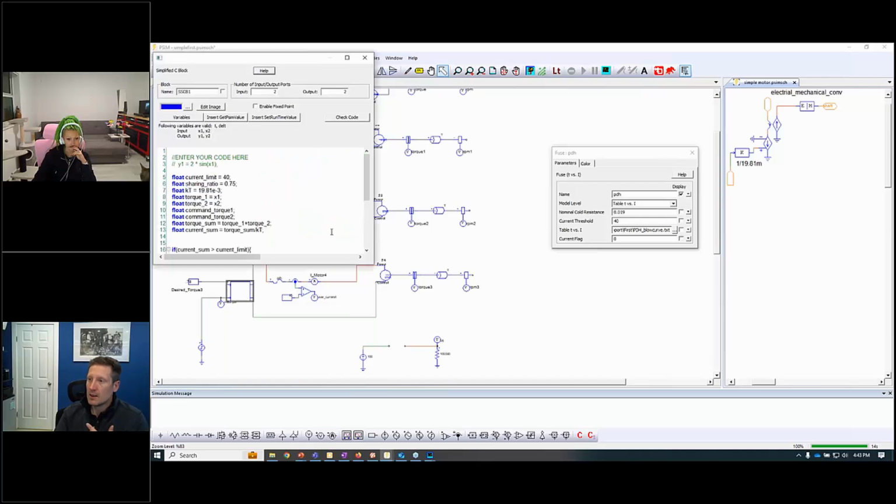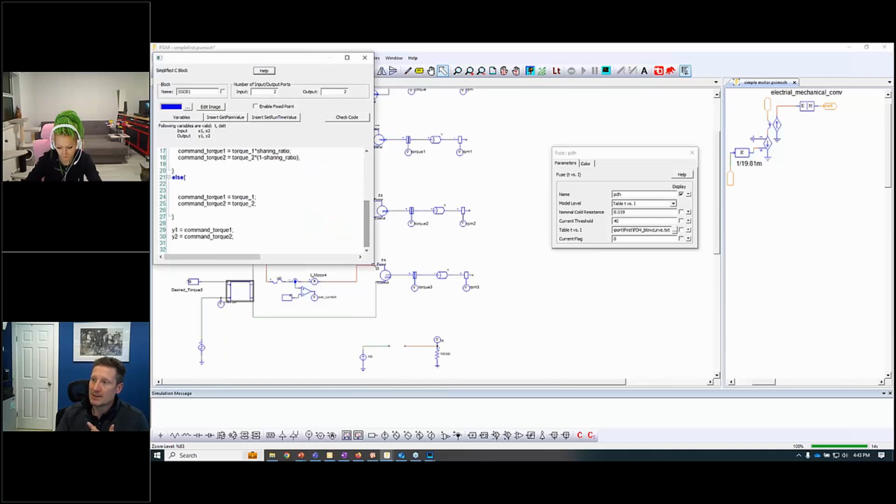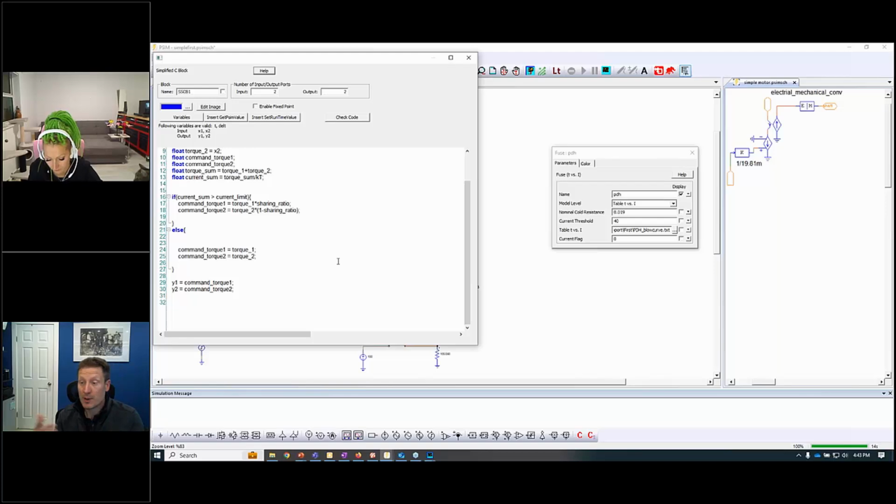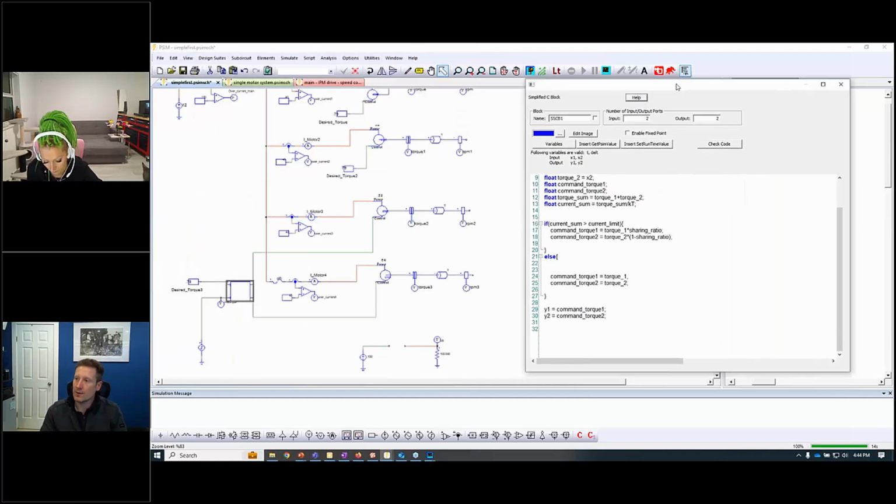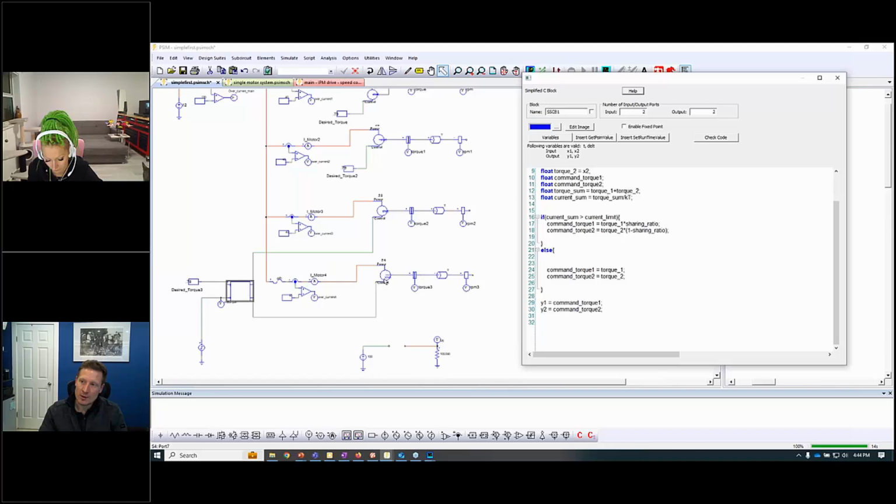You can put that one in series with all of these guys now. And instead of having some really basic logic in here, you could put a timer and track, I've been in an overcurrent state for 10 seconds. That's allowed. And then have a dynamic adjustment. In this case, all I'm doing is limiting these two motors. I've seen some diagrams where there's 10, 11, 12, 13 motors.